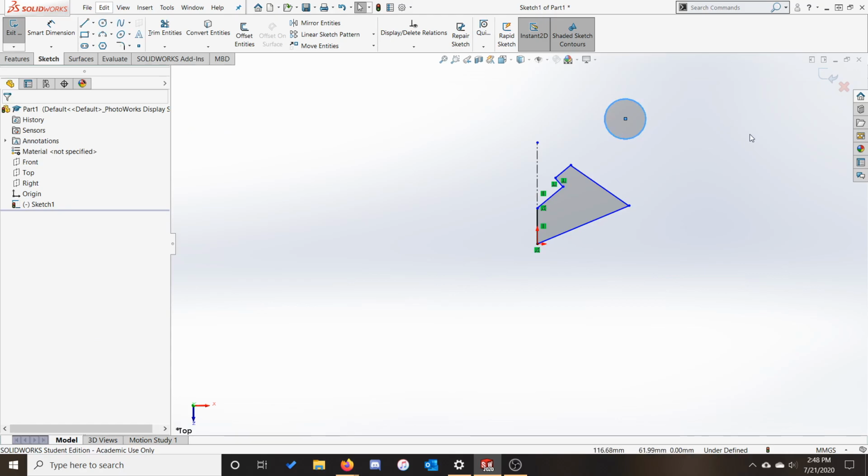Now, before we get too much further into the revolve tool itself, there's a dimensioning trick that I would like to show you. When cylinders and circles are shown in engineering drawings, they're often dimensioned with diameters. However, in a revolve sketch, we only have access to half of the full cross-section of the shape, meaning that we could only really dimension a radial value. We could calculate the dimension by dividing the diameter by 2 and inputting the result, but that would be considered poor design practice. Fortunately, SolidWorks has a trick that we can use here called double dimensioning.